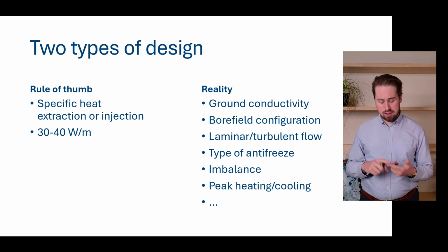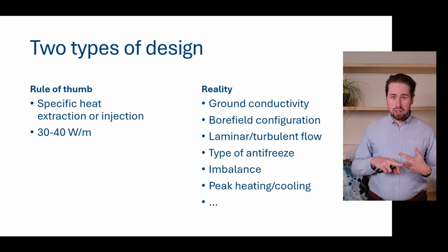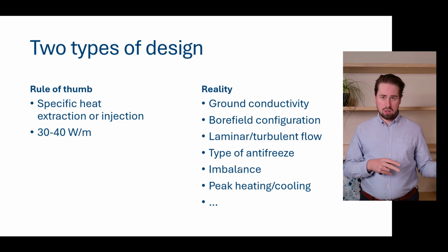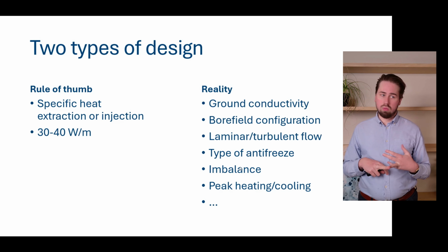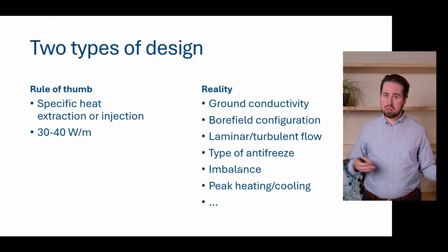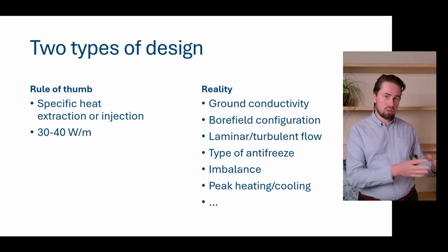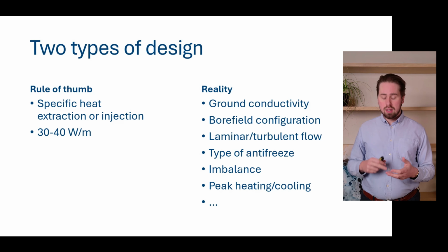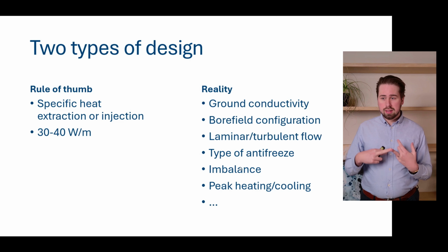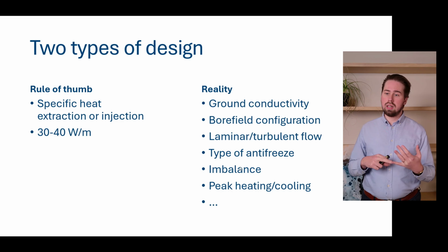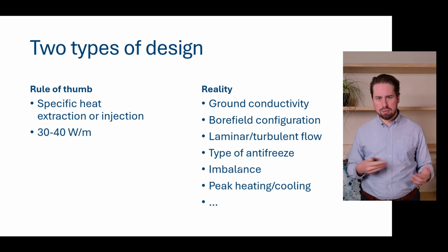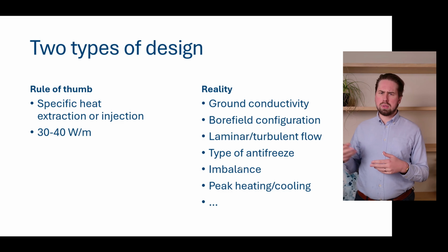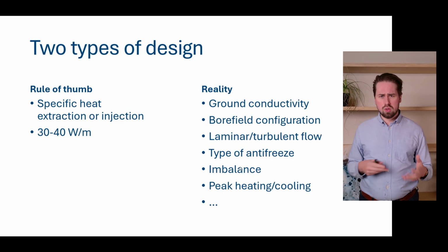Not every project is the same. Soil conditions can vary from location to location. The ground conductivity can be different. You can have different borefield configurations. One project can be deeper boreholes, the other one shallower, more dense together, more apart. We have laminar or turbulent flow rates in our boreholes itself. We have different types of antifreezes that you can have. You have different imbalances of different buildings. You have perhaps a different peak in cooling than in heating and so forth.